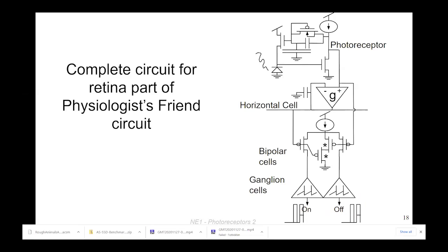They extend over a big extent. Some of them are direction selective. It's not clear. We could have included something like that, but the functionality was not so clear. It's not just taking a difference, a high pass difference. It's hard. And only a couple of people have built silicon retinas with amacrine cell models on them. And the functionality provided by those amacrine cells was never very clear. And they occupy more real estate, right? Any time you put more stuff on the focal plane, you're going to get less fill factor, less area sensitive to the light. So that's still a bit open, what you might use it for.